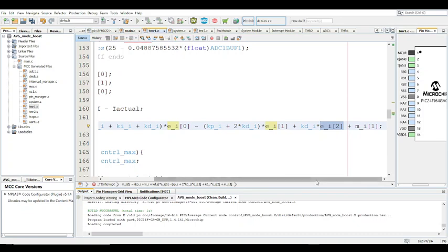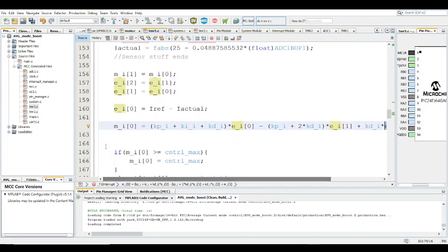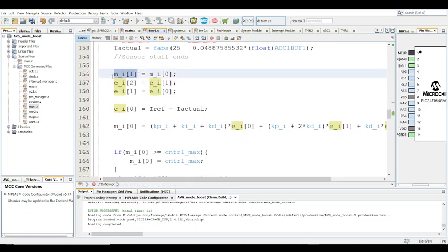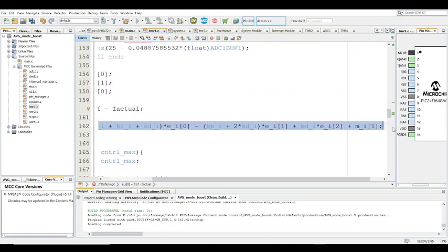And I guess that's the downside of this. You have to keep track of 2 previous error values, but that's fine, as you could just use this. So this is the previous PID output. You equate it to the current PID output, and then you have the second one, two errors ago essentially to the past error, and the past error to the current error, and obviously you update the current error with this equation right here, and then you update the PID, right?